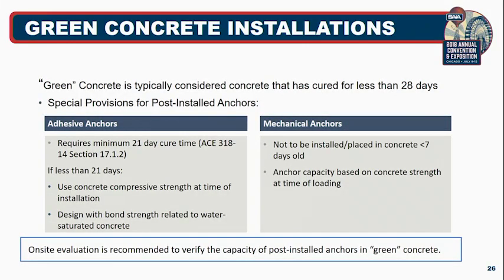Green concrete installations. So the code offers different criteria for how you address green concrete depending on whether you're designing or utilizing adhesive anchors or mechanical anchors. When it comes to mechanical anchors, the basic guideline is you shall not place the anchors in that concrete until it's achieved at least 7 days of cure. That's unless, of course, you've got additives added to kind of speed up the cure time of the concrete.